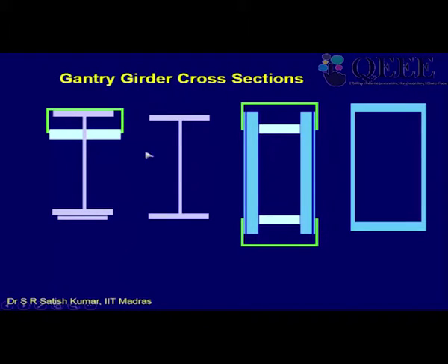Okay. So what is happening is, in this case the channel and the I section, they are welded together somewhere here, but still the entire section is an open section. It is not closed in any way. So it is going to warp and it will not be very strong in torsion. But then since Iyy has been increased, it gives a better performance than a simpler I section. Okay. So that is the one problem.